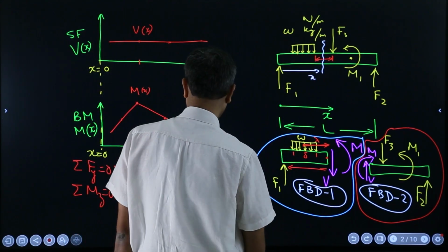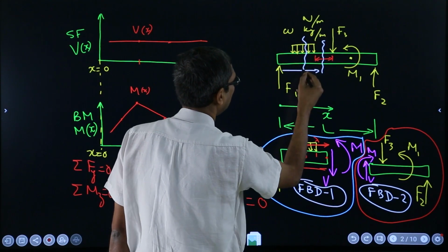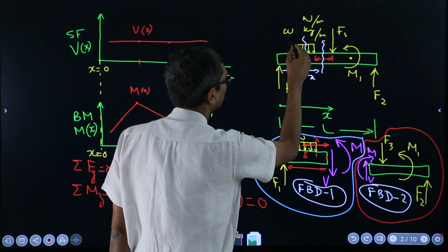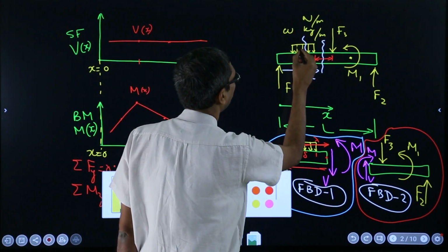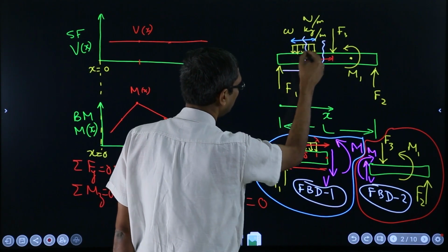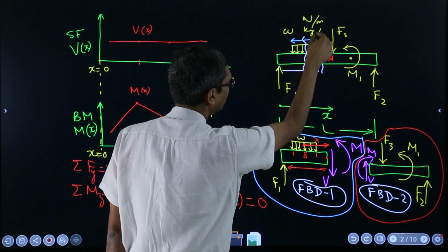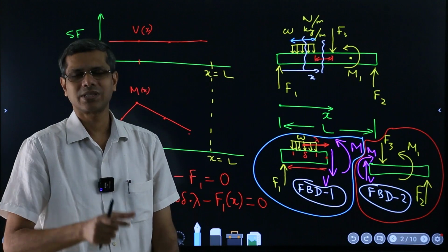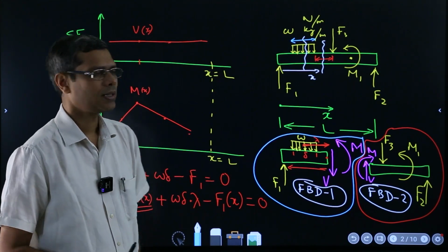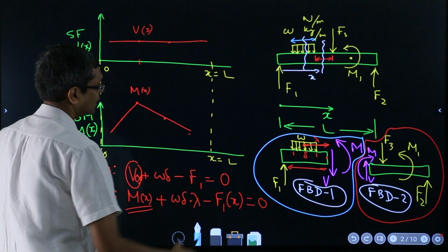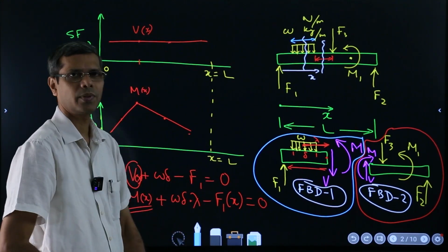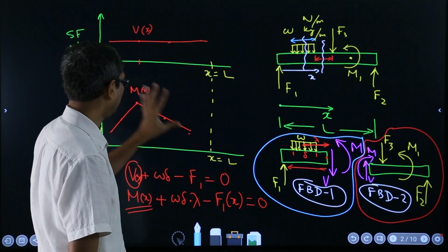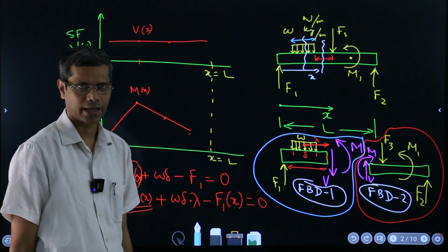Similarly, if you have taken a cross section here, and derived the equation in terms of x, that equation will be valid for everything that happens between this distance, okay, because one thing abruptly happened here and again something happened here abruptly, but nothing changed in between. So in this segment to segment analysis, you can draw the shear force and bending moment diagram segment by segment, in chunks. That is how you should draw, and then the full thing is your full SF and BM diagram.